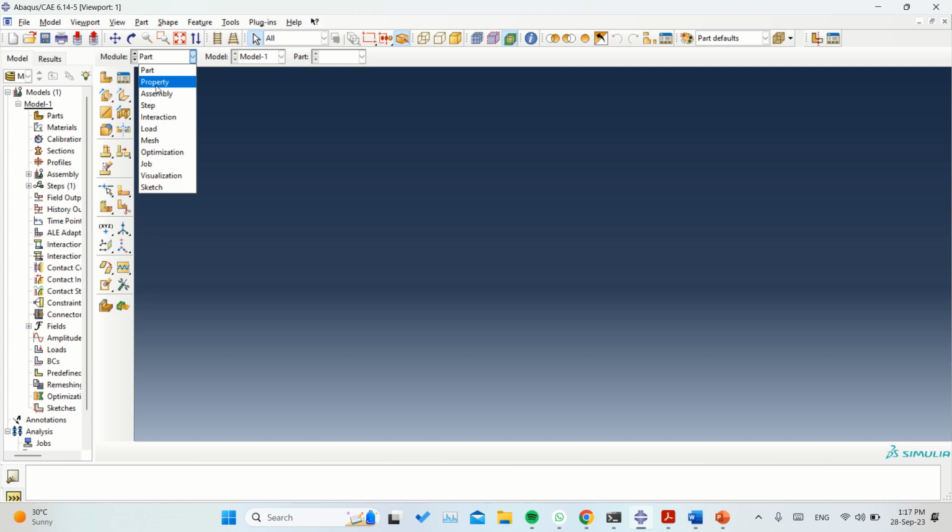If you are defining a circular steel tube here, it will be fabricated, it will be developed. What are the properties of this tube? What will be the strength of this tube? All these properties will be given for this tube. When you are talking about steel tube, it is Q345. The yield strength, the elastic modulus, the section modulus, all the properties are hiding behind this Q345. So the second will be to define the property.